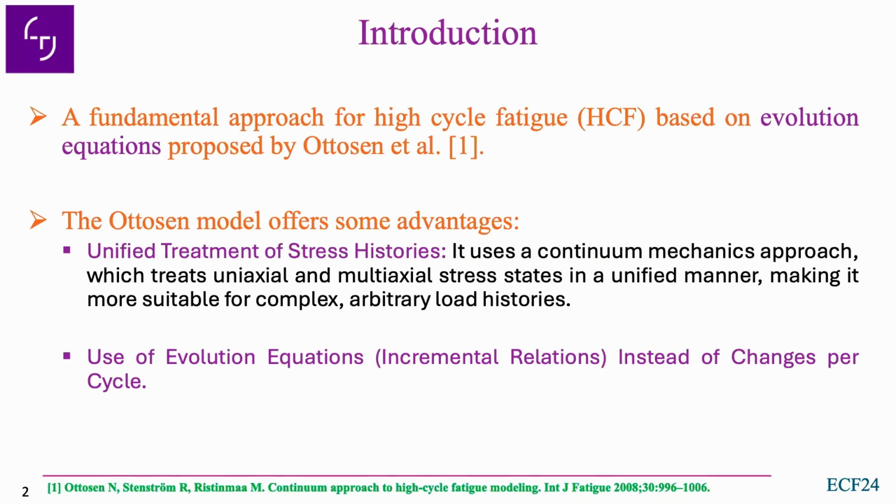It uses a continuum mechanics approach which treats uniaxial and multiaxial stress states in a unified manner, making it more suitable for complex arbitrary load histories. And it uses evolution equations, incremental relations, instead of changes per cycle.